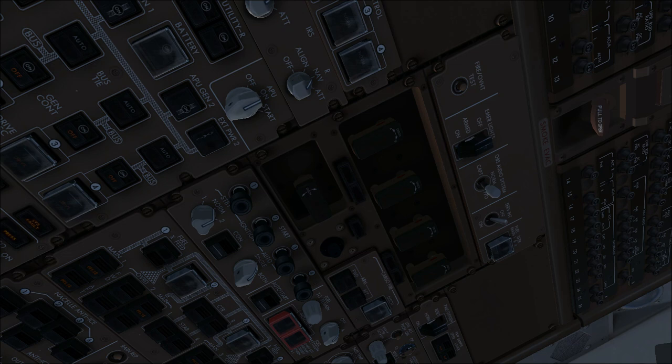At this moment, after fuel transfer main 1 and 4 switch off checked, we go to the fire panel. Fire panel set, you have to check all the engine fire switches are in, and this is checked. The bottle A discharge and bottle B discharge lights must be extinguished. Those two lights and those two lights checked.